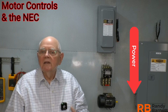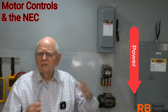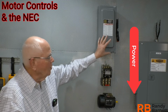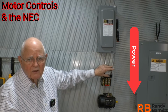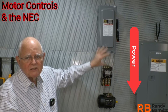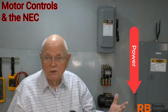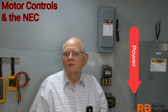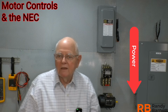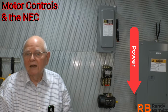Quite often, all of this stuff we're talking about, this motor, the fuse disconnect and the motor starter that we're going to talk about down here, may be inside of one control cabinet. In industrial and commercial facilities, it may be inside of a motor control center bucket, a motor control center cubicle, in other words. And then, of course, we have our motor down here. The motor's going to be wherever it is out in the plant.